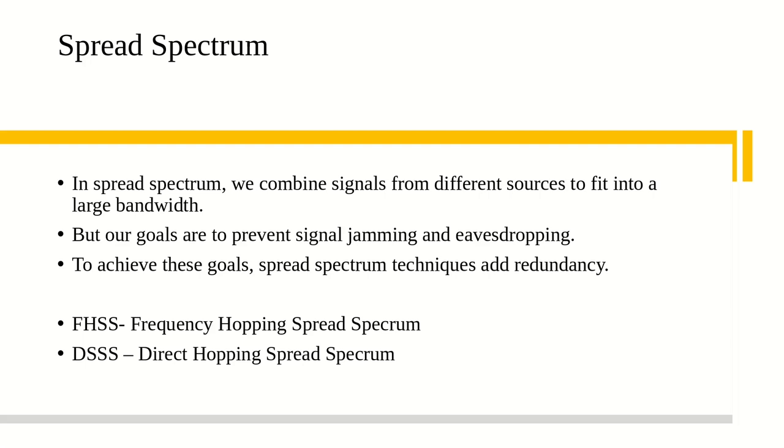A signal that occupies a bandwidth of B is spread out to occupy a bandwidth of B_SS. All signals are spread to occupy the same bandwidth, B_SS. Signals are spread with different codes so that they can be despread at the receivers. Signals can be spread in the frequency domain or in the time domain.